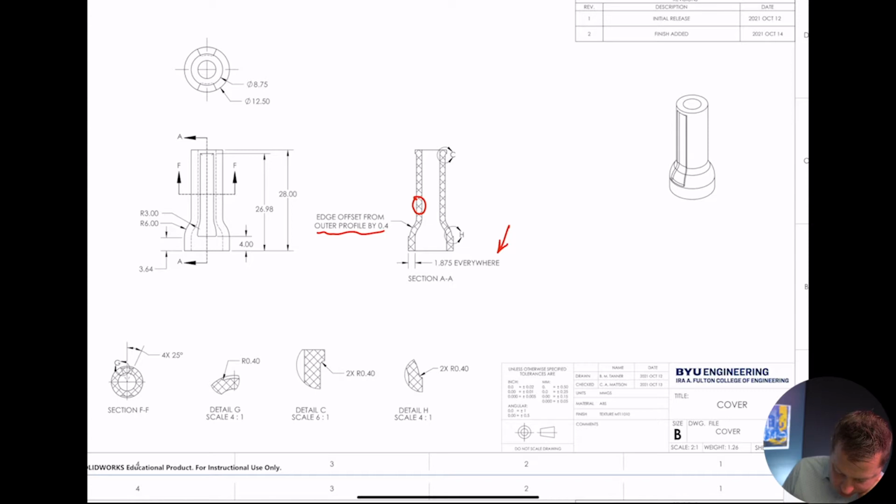So when I have things that give me a constant thickness everywhere, I'm pretty much going to want to do a shell. So what am I going to do? I'm going to do a profile like that, revolve it around the center axis, shell out the middle, and cut out this little piece that's right here, however that is. I'm going to cut out that little piece.